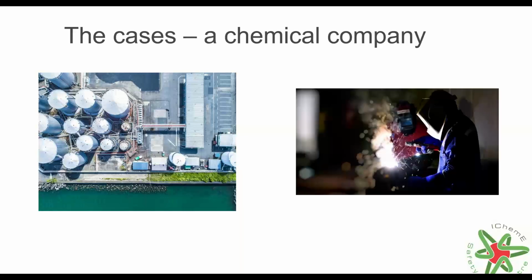In terms of some of the key findings for that particular incident, work on these tanks had commenced when all 3 tanks were out of service, but due to delays and a scope change of repairing the agitator support, Tank 2 and 3 were returned to service, meaning their isolations had been removed. The presence of a common vent valve meant that vapours could travel between those tanks. Tank 1 was not adequately isolated or vapour-free when the welding took place. The late change of scope meant that the work was not planned as part of the initial shutdown activities. The permit to work form was not completed thoroughly, skipping the section discussing potential flammable atmospheres.